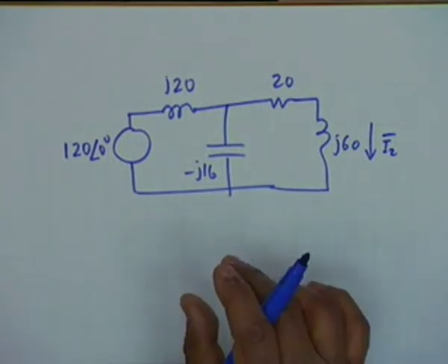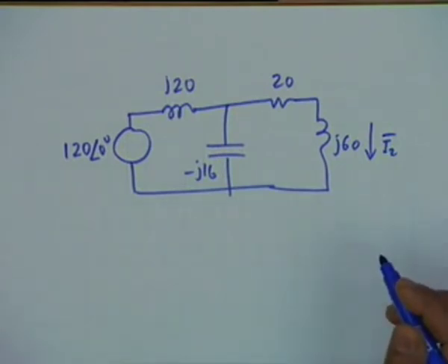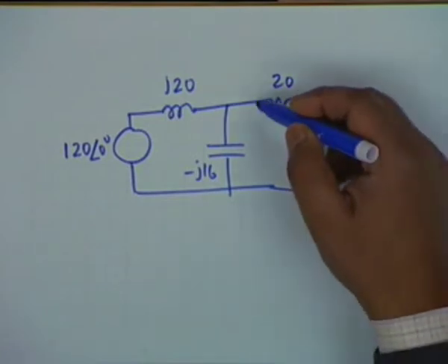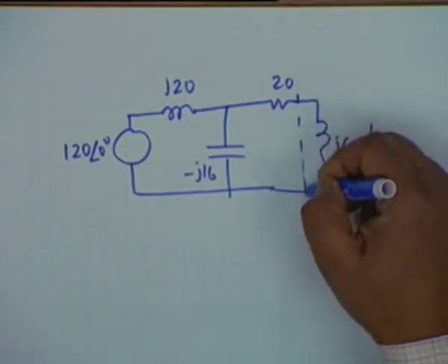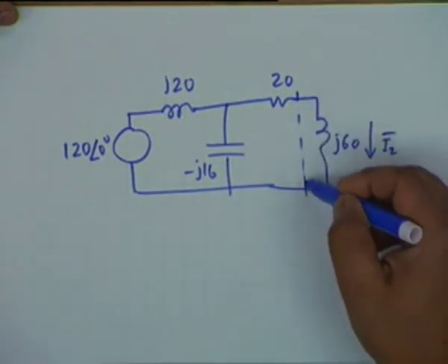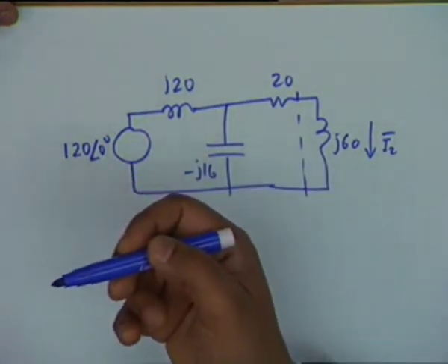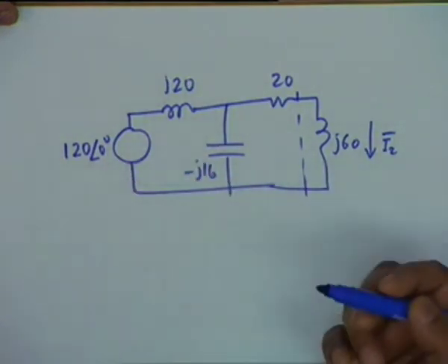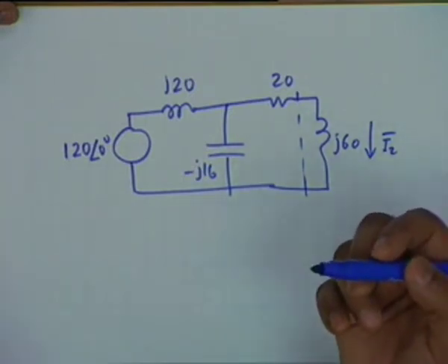Thevenin's and Norton's theorems are valid for AC phasors also, and these are also very important tools for solving a complicated network. For example, if I apply Norton's theorem to find out this current, then you short circuit this, find out the short circuit current, and then you find the equivalent Thevenin impedance. This can be done, but can you suggest a better procedure?